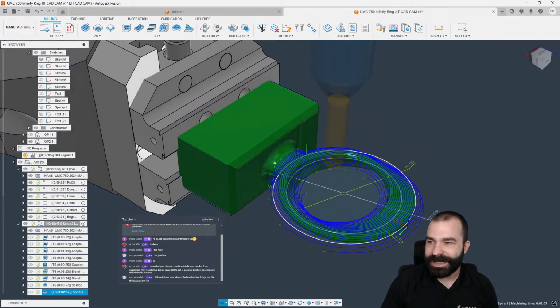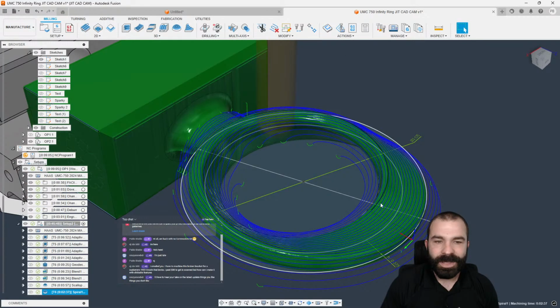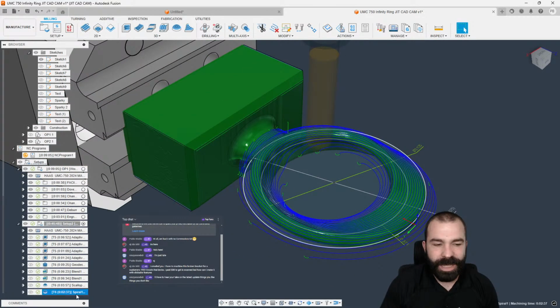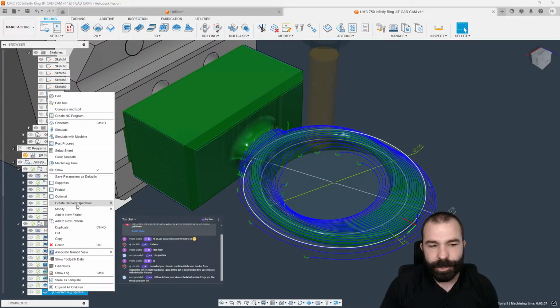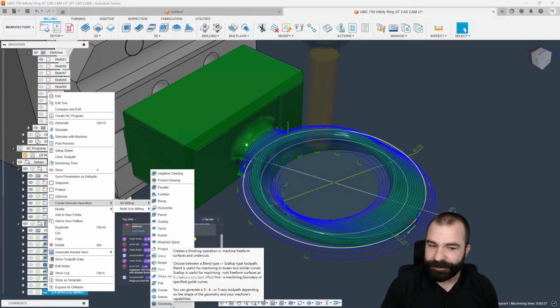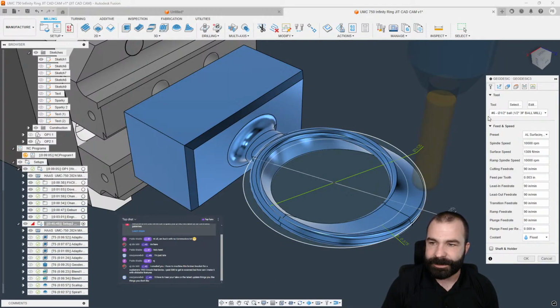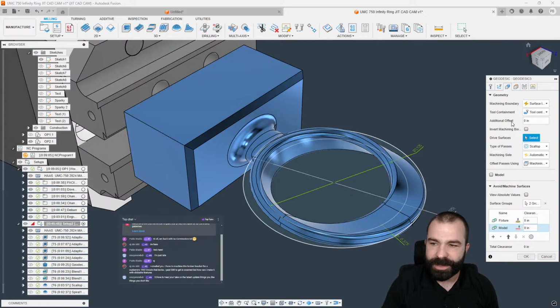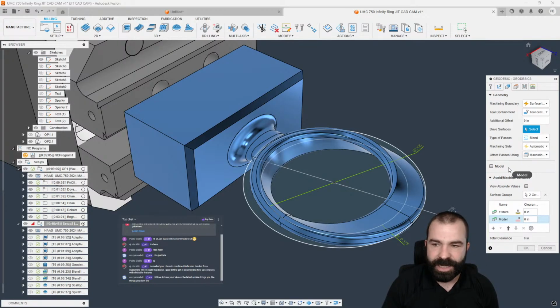So as you're seeing, again, in real time, we're utilizing different toolpaths with nothing more than the drive operation. Again, this might be a really good kind of profile where I did see some geodesic stuff. Now, if we go geodesic, you do have the ability to actually go through and do something like a blend strategy. You could actually do a circle at center as well.